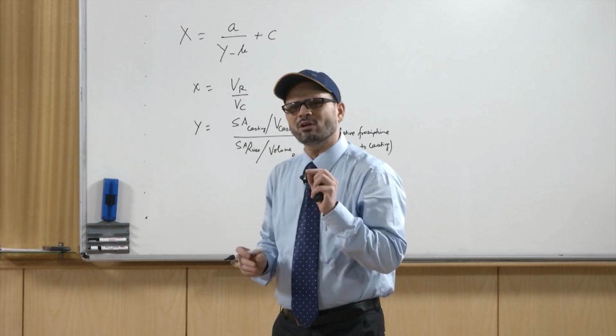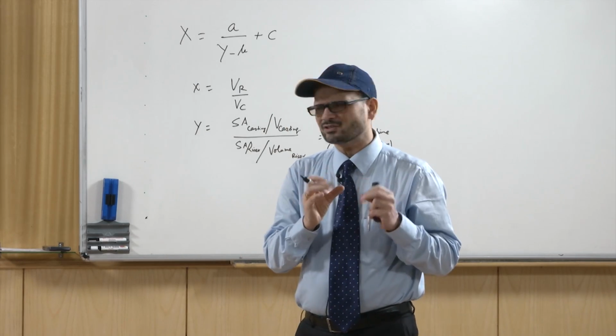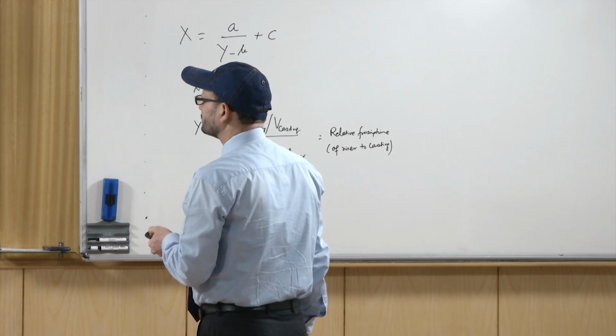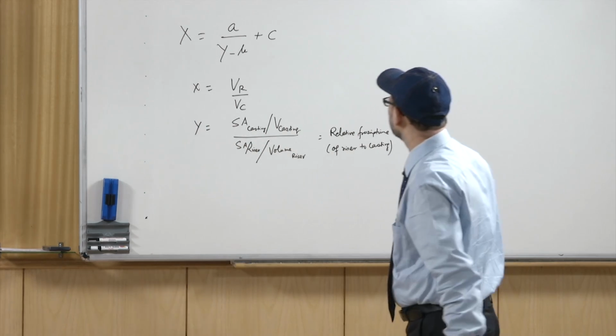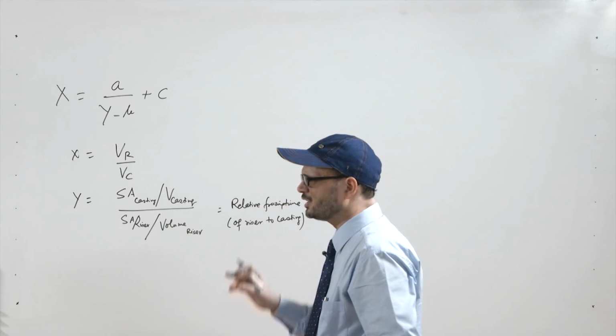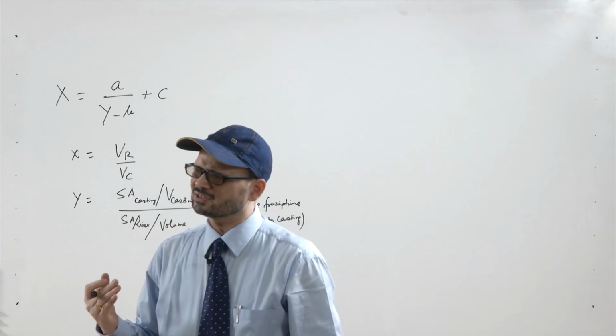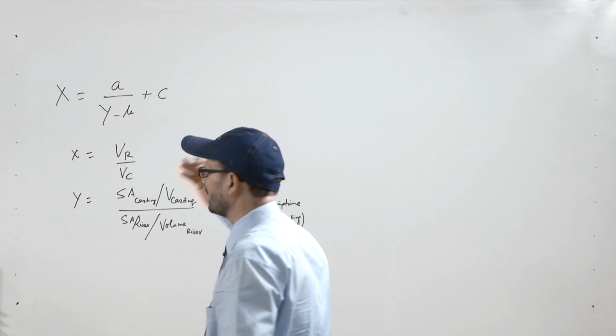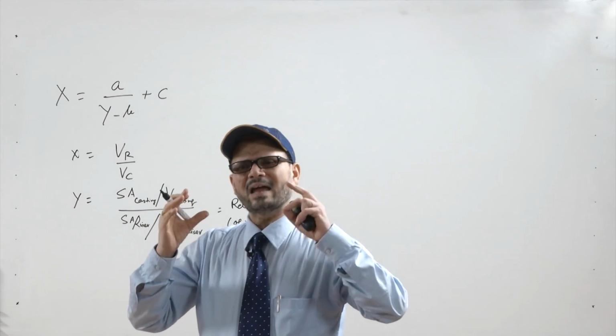So, smaller volumes can suffice. That is basically the essence of his findings, and this way once you develop one equation, you can solve that equation and get the values of the riser dimensions.